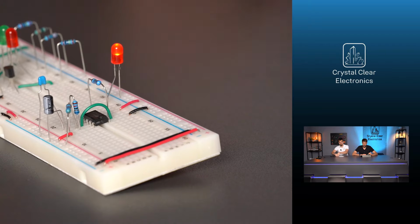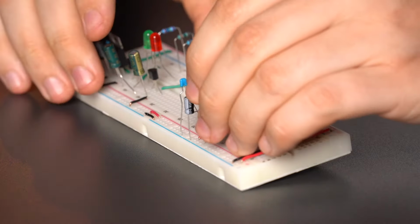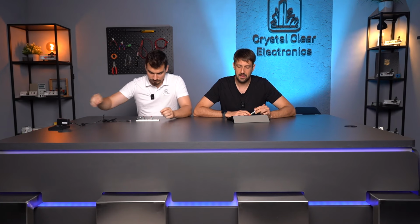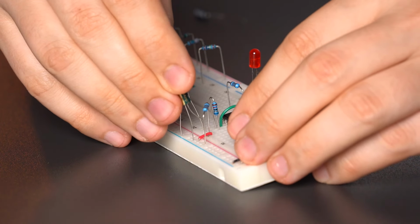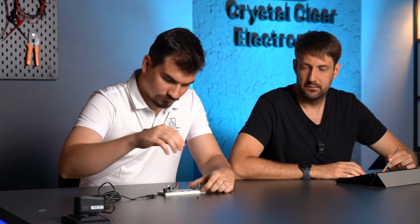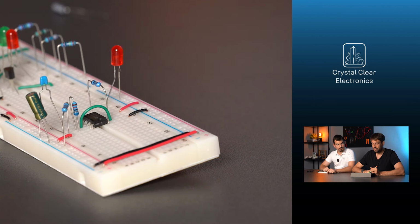Put the 1 kilo ohm resistor back in place of R1, and replace C1 with a capacitor of 22 microfarads. The blinking speed will then be halved, while the LED is lit for about the same length of time as it is not. If you decrease the value of R2, the blinking will become faster, and the time difference between the two states of the LED will increase.